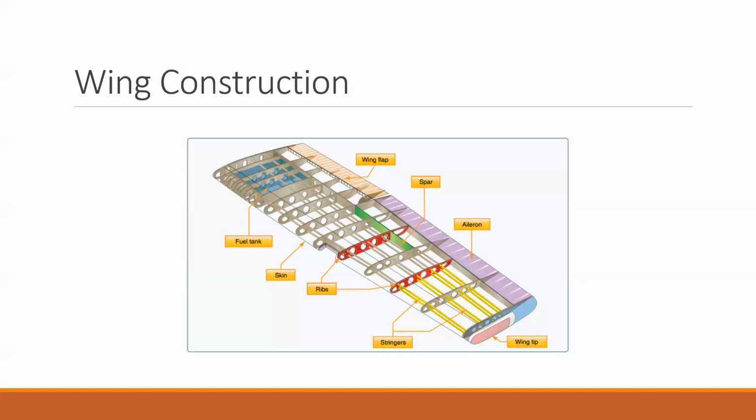Inside the aircraft wing, you have all these middle sections that are the same shape as the wing. These are called ribs, and these ribs provide structural support along the wing surface, because usually the wing surface is made out of metal or carbon fiber or something else, fiberglass even. And these ribs just provide support to that frame, because the wing does have a very specific shape that it needs to keep in order to generate lift efficiently.